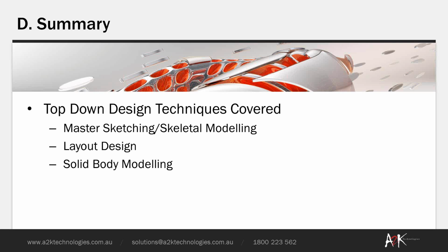Some guys will tell you it's better for consumer goods and plastics, which it can be used for, but I've also seen guys create very, very large assemblies using solid body modeling. So the question you ask yourself is, what sort of changes you want to make to your assembly? And that will dictate which technique that you need to use. So in my opinion, the ones I see used the most is solid body modeling and master sketching. So they're typically used over and over again by lots and lots of people.